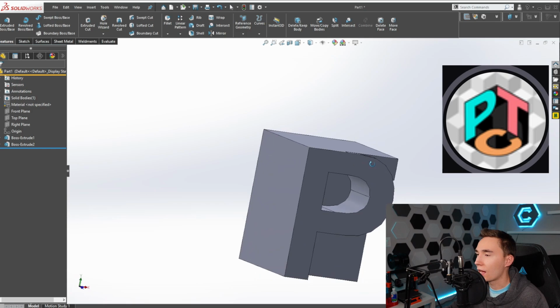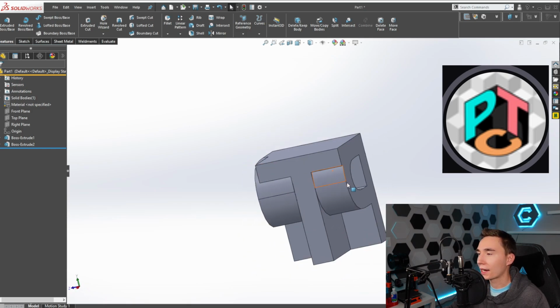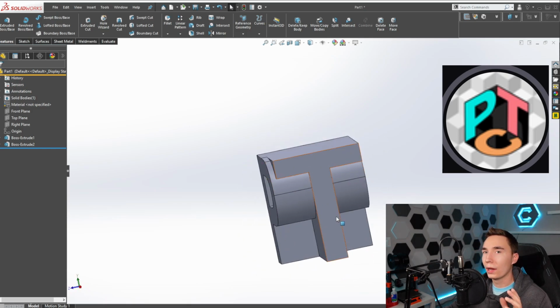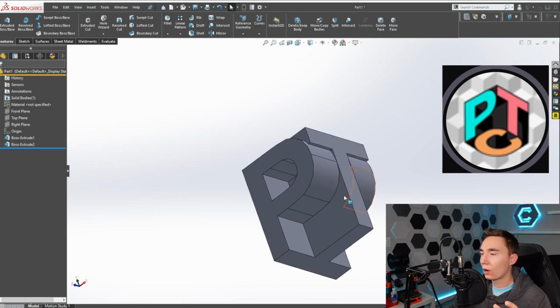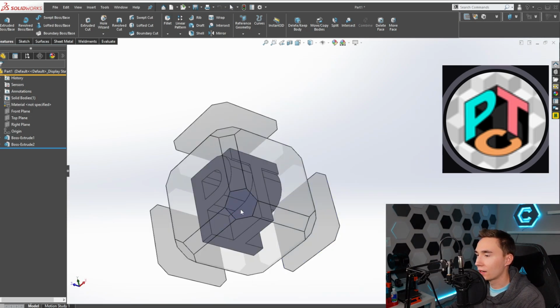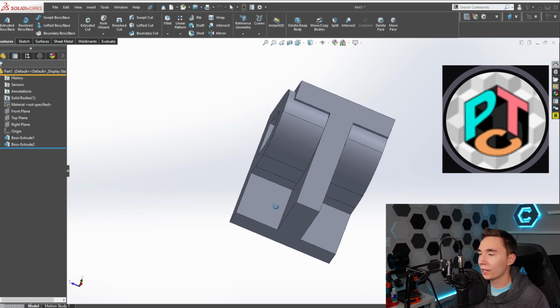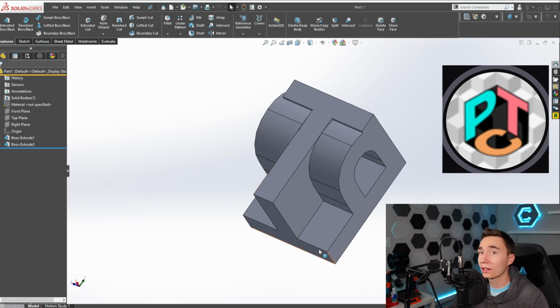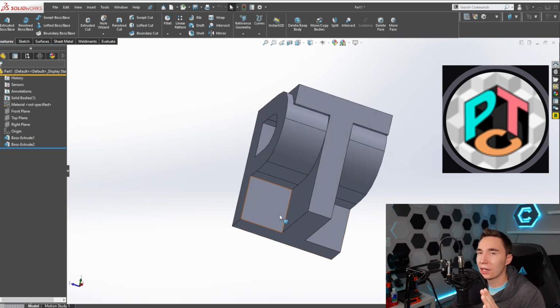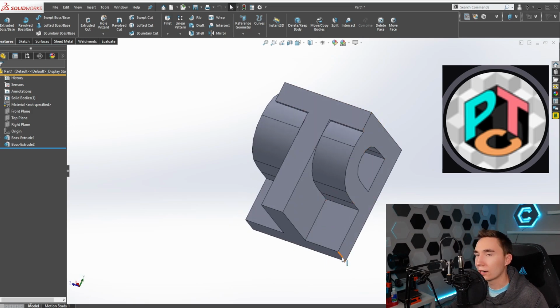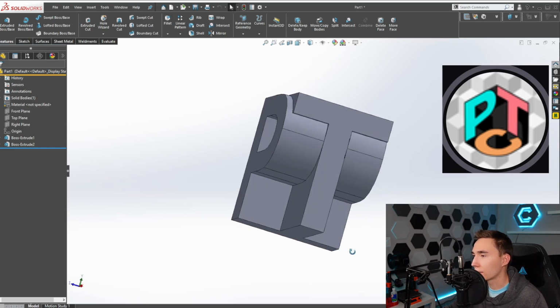And then you can see I extruded it all the way back. That's because when we go to set this up, we eventually want this to sit in the air like this on the shelf. We want it nicely sitting back, just like the logo is drawn. So in order to do that, we need some sort of support in the back later. That's why you can see I made it a 1/2 inch, but then I realized I need something all the way back there. So I extended it all the way to the back corner, and then later we'll build our mount off of this back little edge right there.